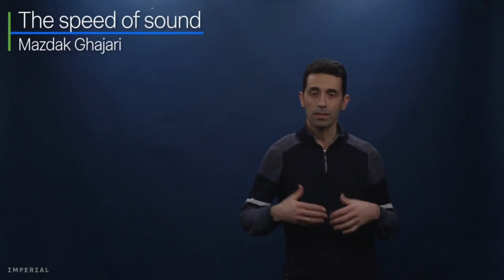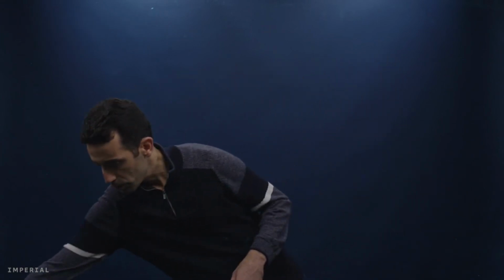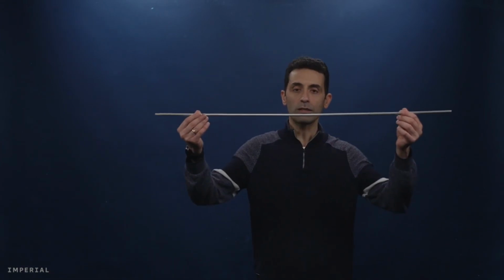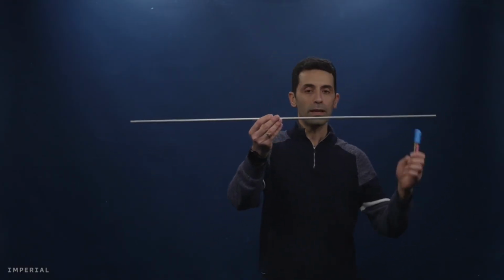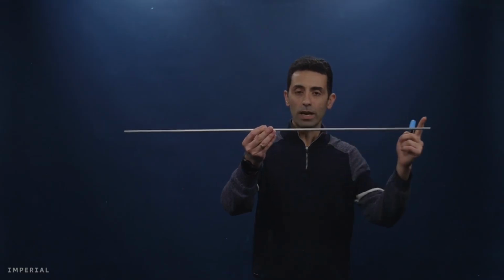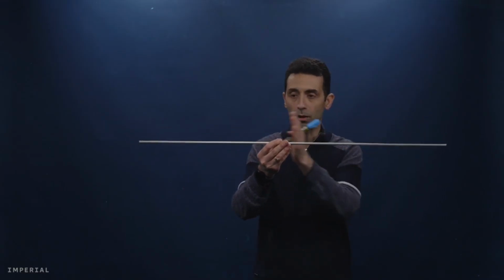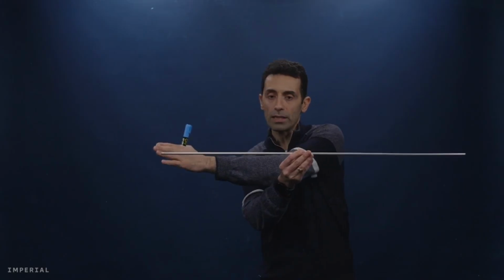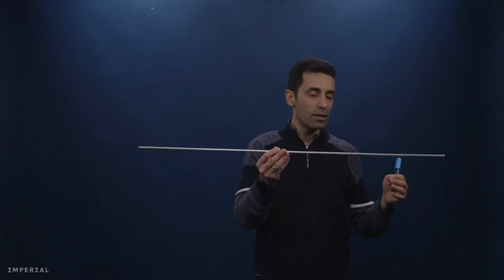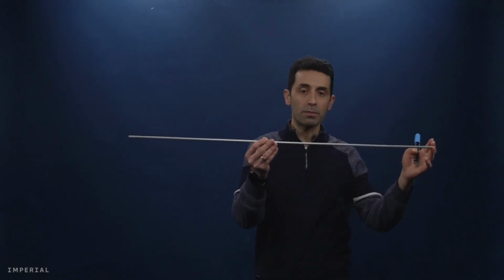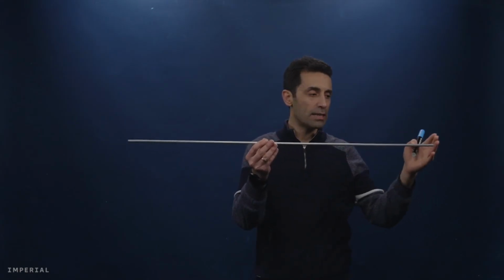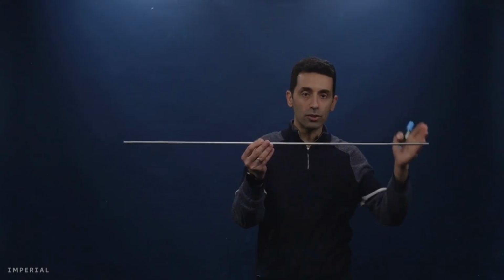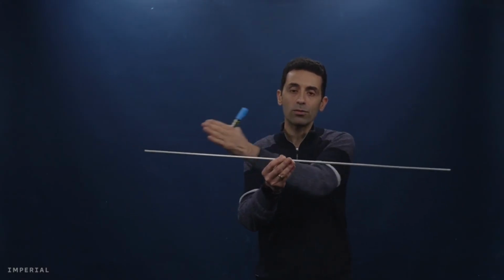Speed of sound is the speed at which sound travels within a medium. So imagine this rod here. If I hit one end of the rod, there is a stress wave or strain wave that travels along the length of this rod, reaches the end and reflects back. So really the speed of sound, or speed of dilatational wave, in our rod is the speed at which this initial wave that I'm creating travels throughout this rod.